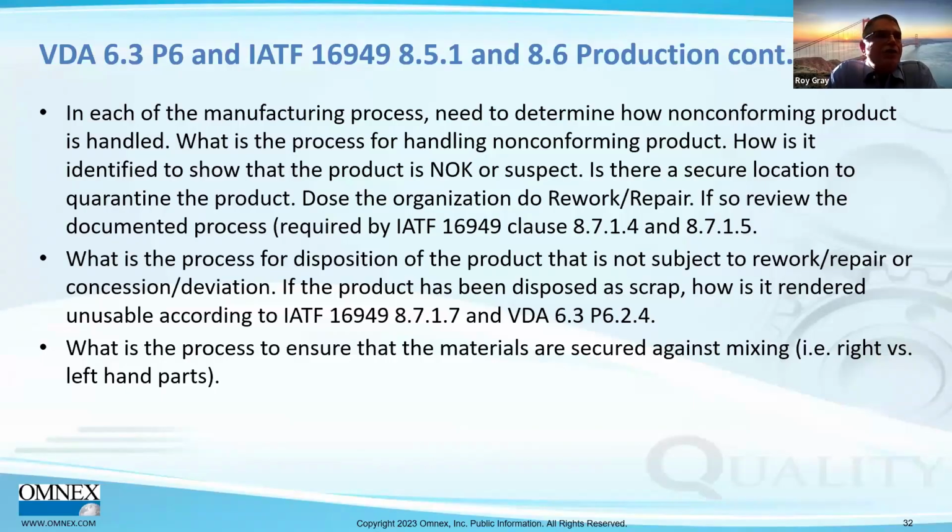Does the organization do rework and repair? If so, IATF says we need to have a documented process for both. And if we're doing a repair, we have to have customer authorization before we can start the repair. You'll see that in clauses 8.7.1.4 and 8.7.1.5 of IATF.